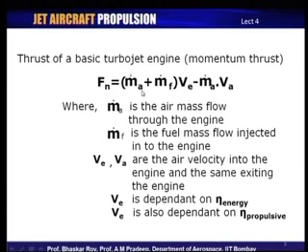Now, what we see here, it has two mass flows, the air mass flow which has come into the engine through the intake system, and the fuel mass flow which has been injected into the engine into the combustion chamber, and two of them together make up the high energy gas that is going out, and that creates the reaction force created by the nozzle, let us say.